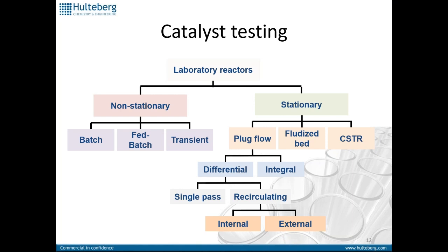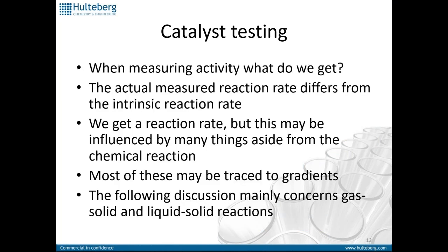But given these different types of reactors, there is one very important question that we need to ask ourselves, irrespective of what type of testing we're doing. And that question is, when we measure activity, what do we actually get? So we measure a reaction rate. And most likely, that reaction rate will not be exactly the reaction that happens on the surface. So we're not going to measure the intrinsic reaction rate.